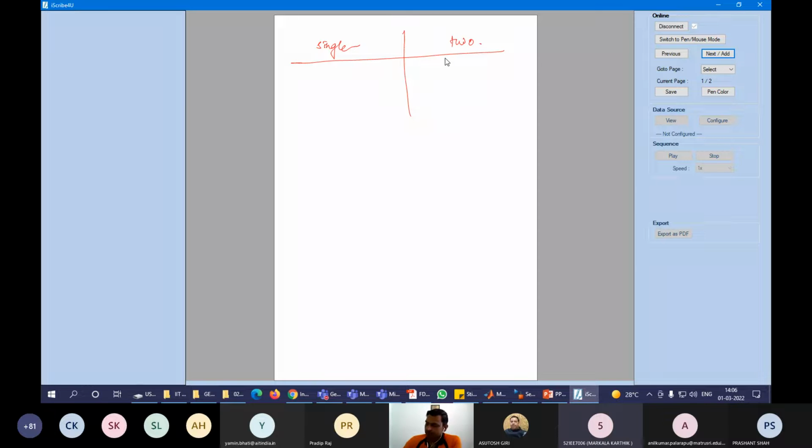When the PV array available voltage is less, then the 2-stage is better. So again, I am going to modify your statement. Boost converter is not used to boost the voltage in grid connected PV system.